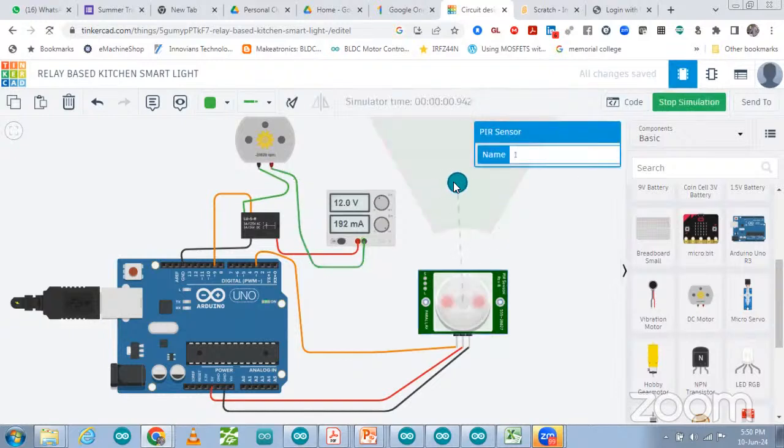If there is any motion, you can see the motor is turning on with some RPM. RPM is showing negative over here. Why is it so? Because positive we have connected with the negative, and negative we have connected with the positive. That's why RPM is showing negative. Negative means the direction is anti-clockwise. Nothing else. It is working. Otherwise it is not working over there.